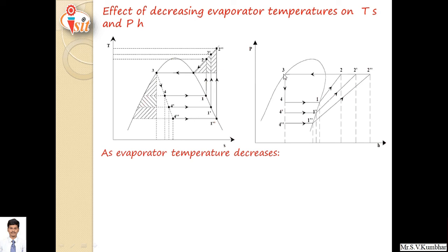Here at 3 the refrigerant is converted to liquid, that is, high pressure low temperature liquid refrigerant. This liquid refrigerant then flows to the expansion valve where its pressure drops down, and again it is sent back to the evaporator where it absorbs latent heat from an object which is to be cooled and is converted into vapor, and the cycle continues.